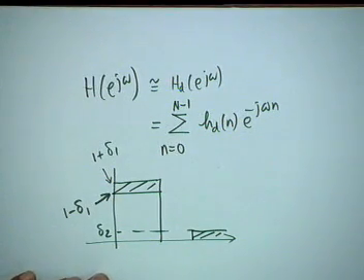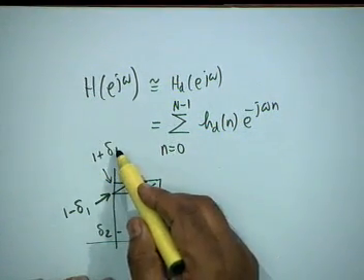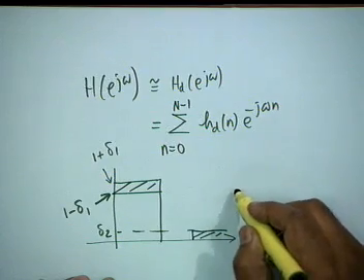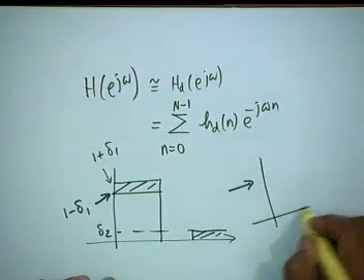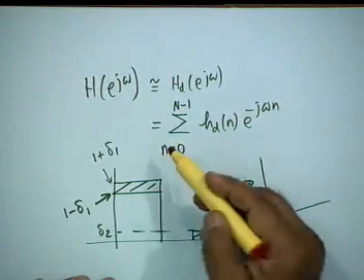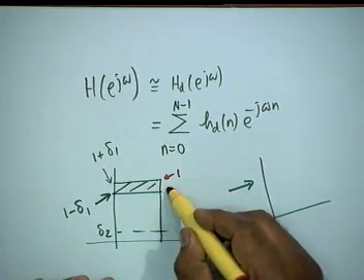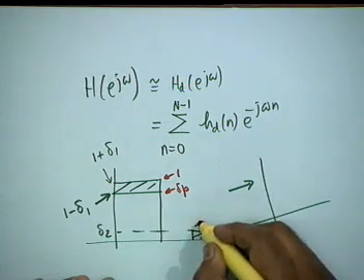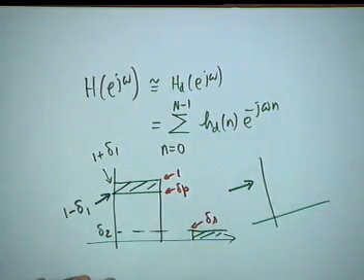The empirical formulas are in terms of delta 1 and delta 2, but converting to our specs, we take the maximum as 1, the pass band minimum as delta P, and the stop band maximum as delta S.